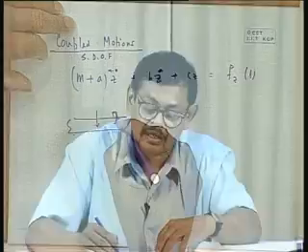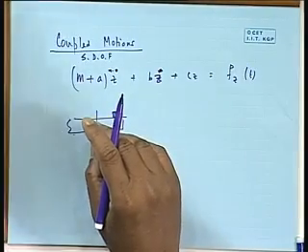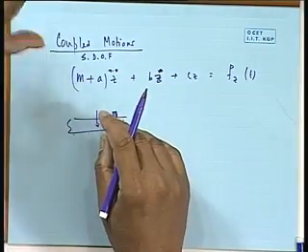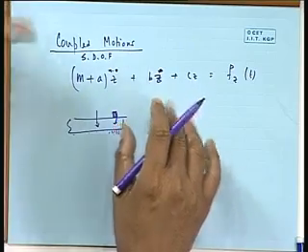If I put a weight here, what happens? It undergoes trim, but it also undergoes parallel sinkage. In other words, if I wanted to trim it, I will find that the trim will necessarily cause a parallel sinkage, because the ship trims about the LCF. So if you just trim the body, its mean draft has changed. This means pure trimming is not possible, unless of course the LCF is at midship. So if you trim it, it necessarily may induce heave.